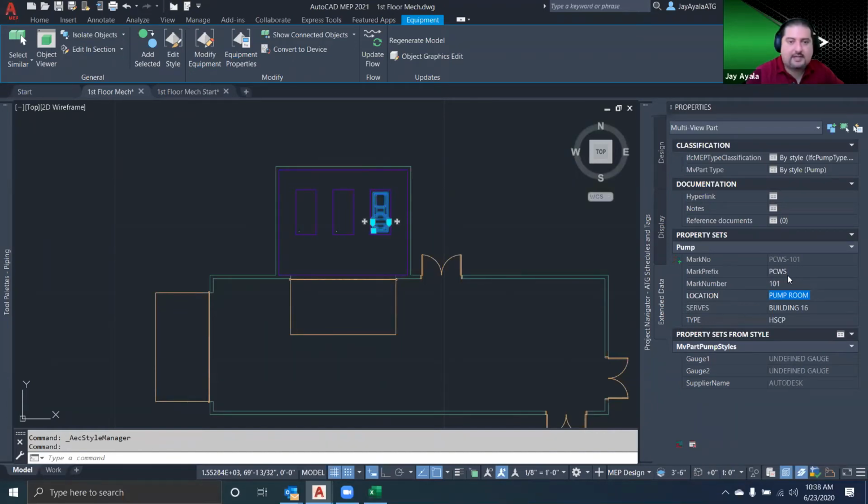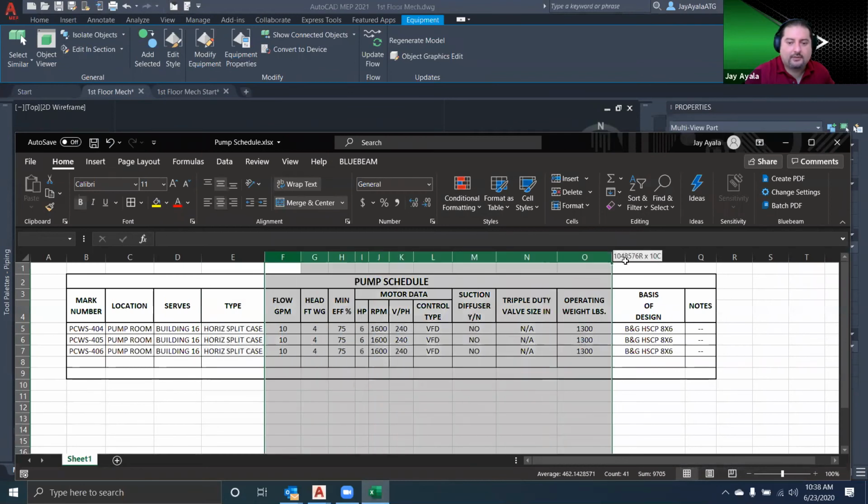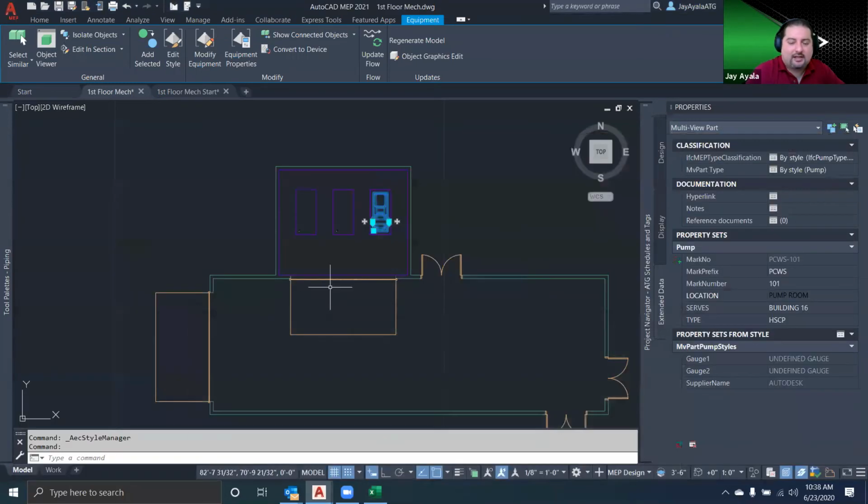Okay, so obviously I would continue down this thread here and make all of these other columns property set definitions. I wanted to show you the mark number in particular as a special case. We're not going to do every one of these for time saving purposes, but this is how we go about making the property set definitions. That last little key there is making a formula and leveraging how that then concatenates itself.